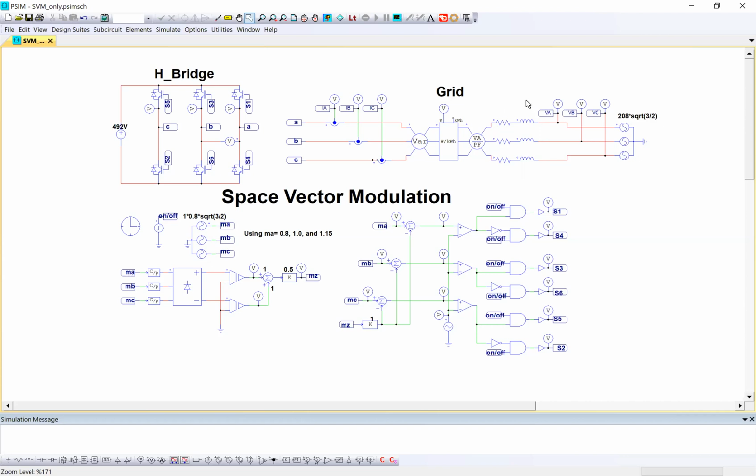I still need to put in capacitors for power factor correction and as a voltage filter, so that when you get to the grid, it's actually a clean 208 line to line. So that's all I have to show you from a current working project that I'm doing.